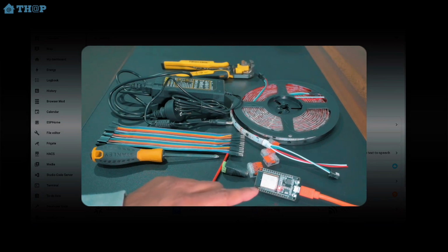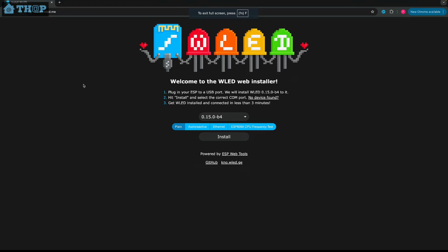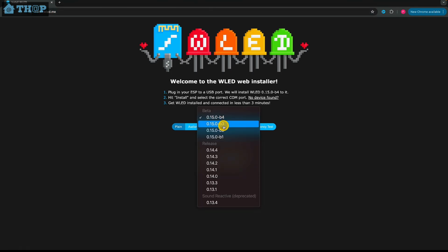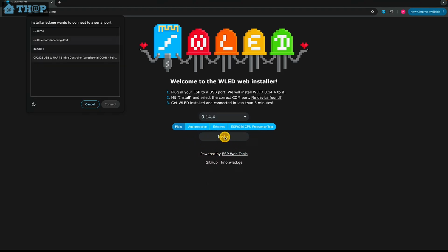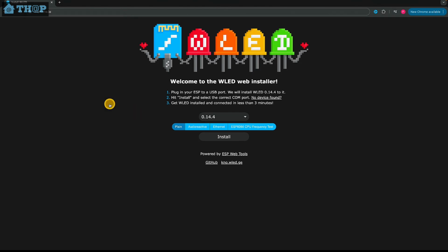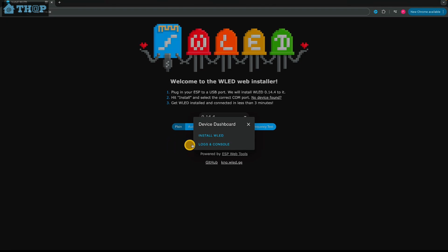Let's go ahead and set up the WLED software. To download and install the WLED software, you need to go to this website, which is install.wled.me. I'll leave the link in the description, and here you can choose a version. By default it selects a beta version, but I would like to select a stable version, so 0.14.4, and then I'm going to hit install. And if your ESP board has been detected correctly, you should see an entry like this. So hit connect, and as you can see, it gives an option for install, so click on install and install.